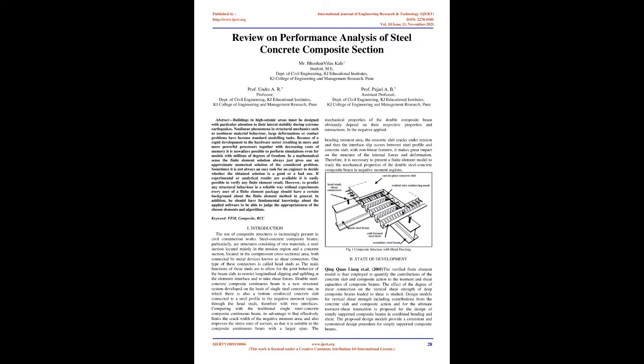Introduction. The use of composite structures is increasingly present in civil construction works. Steel concrete composite beams, particularly, are structures consisting of two materials, a steel section located mainly in the tension region and a concrete section, located in the compression cross-sectional area, both connected by metal devices known as shear connectors. One type of these connectors is called head studs, as the main functions of these studs are to allow for the joint behavior of the beam slab, to restrict longitudinal slipping and uplifting at the element's interface, and to take